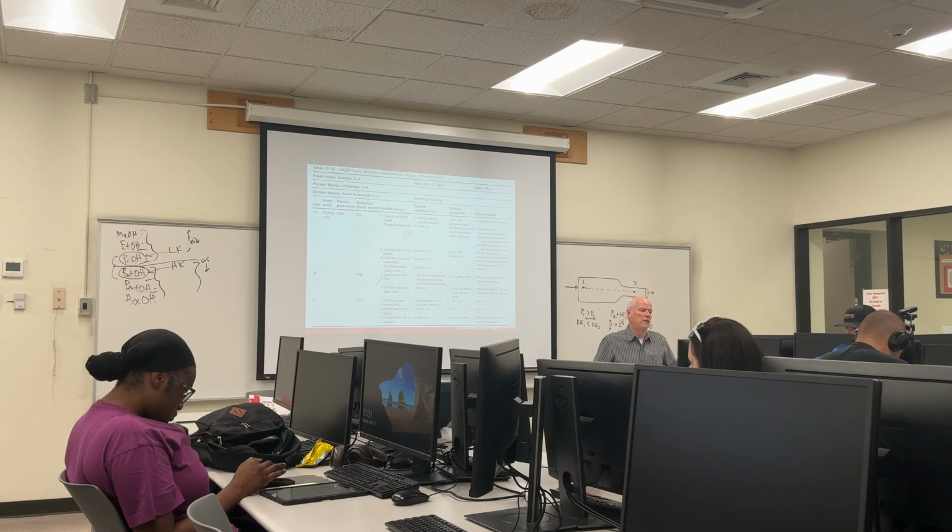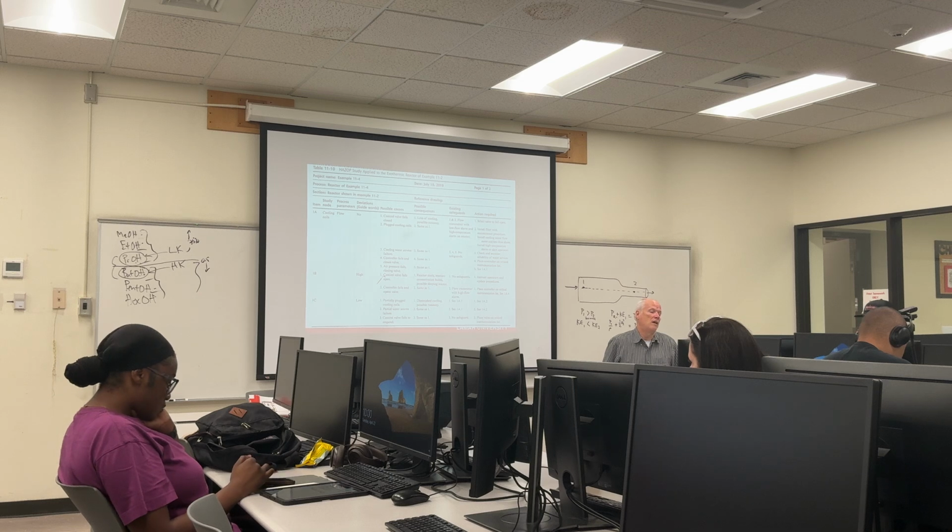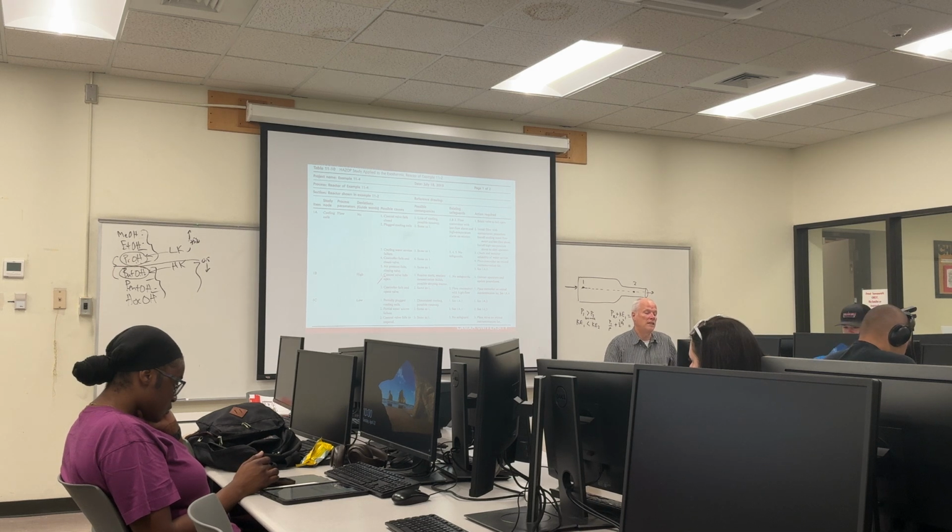You can fail it either way. You can have plugged cooling coils that would cause a low flow or no flow. You could have cooling water service failure. It could be a combination of those two. Well, that was low flow, but air pressure fails. That's assuming it's a fail-closed valve. If you say the air pressure fails,